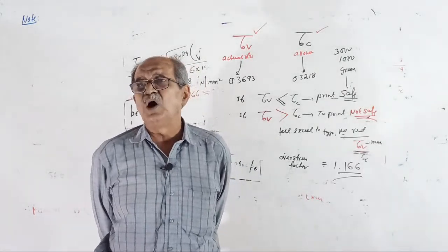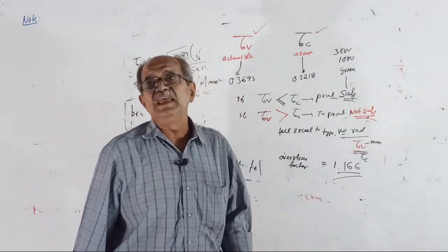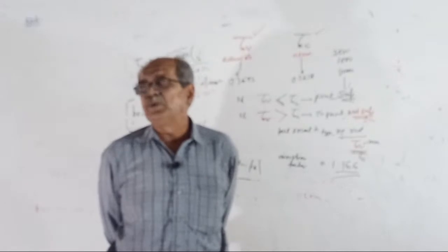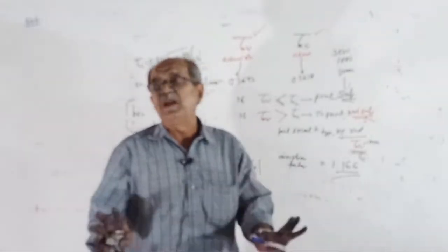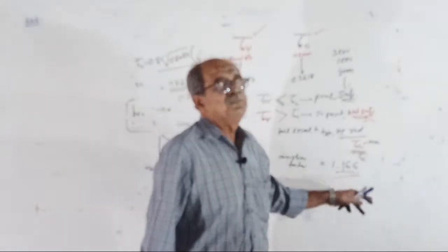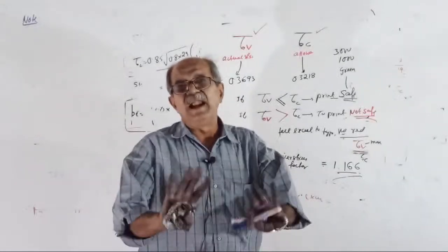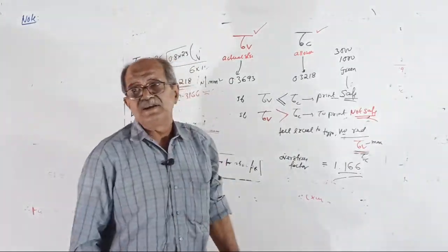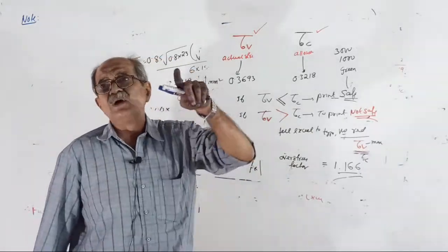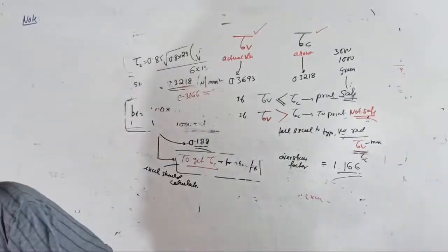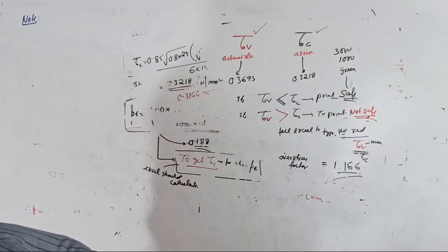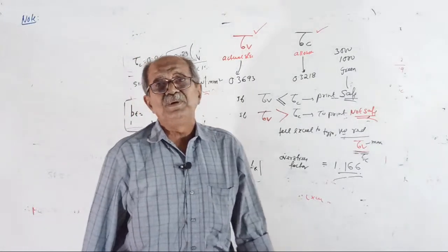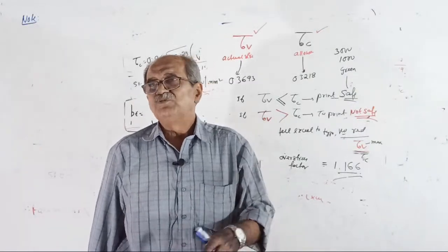So therefore, your choice. If it is 1.03, 1.04, 1.05, etc., you can go to adjustment, increase steel. If it is above 1.1, some people will tell, better, instead of 450, go for what? Don't try artificial. Better go for a depth of 450 or 500, or sorry, 500 or 550.